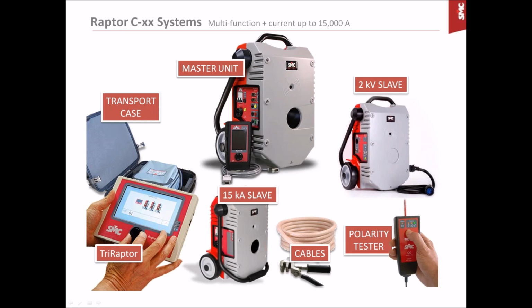And also you have here the connections that we will use to measure the secondary current output. Okay, so we are measuring the secondary current output, and I have also made additional connections for voltage measurements, also for the second test that we are going to do, which is the magnetization test or knee point measurement.